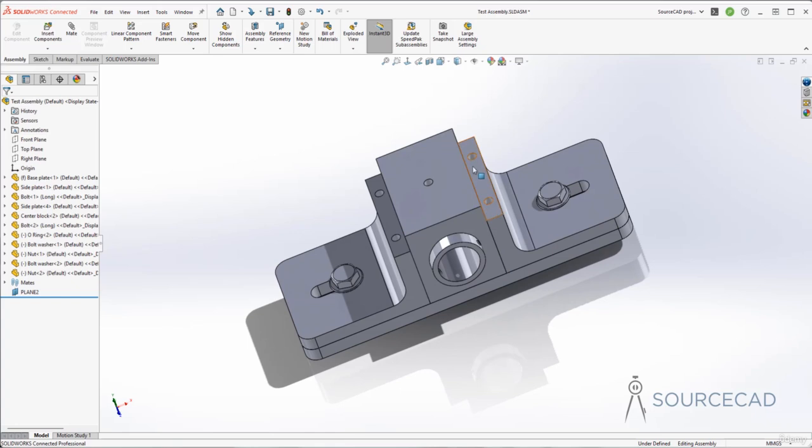We have 4 grooves, and if you just need to add 4 nuts or maybe screws here, then that's going to take some time, and you actually don't need to do it. We have a direct method of creating an array, and using that array you can add just one component in any one of these grooves, and then you can just make copies. Let's see how it works.